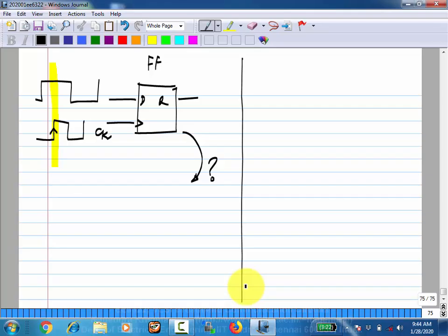I mean, if you have a small signal and you want to determine the sign, what is the first thing you would do? Comparator, yeah. How do you make a comparator? Op amp. It's an amplifier, right? You basically need to make an amplifier. If you amplify it by a large enough number, then it will saturate to the rails and it will basically give you the sign of the output. Okay. So you don't want to use an op amp as a comparator, but anyway.